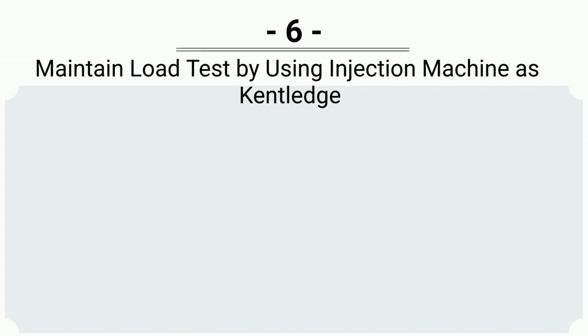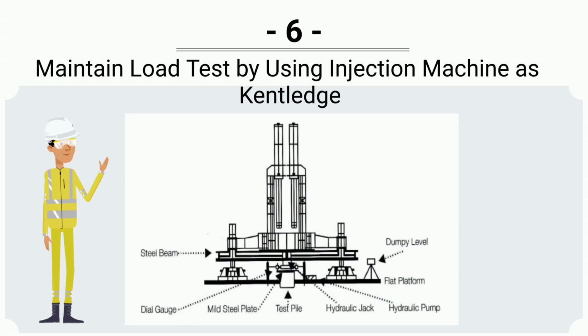Maintained load test by using injection machine as Kentledge. The injection machine, steel counterweight and steel beam sections make up the whole static load test system, in which the independent hydraulic jack imposes vertical force on the test pile.